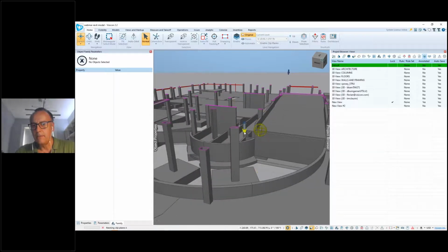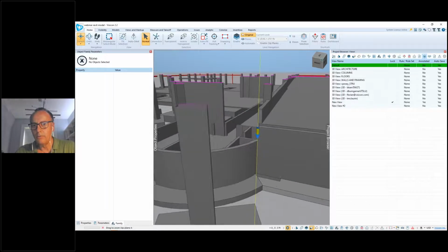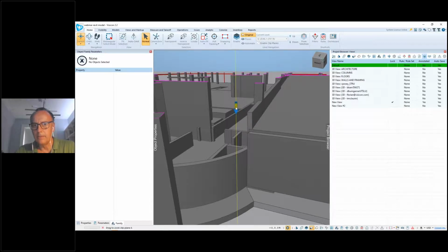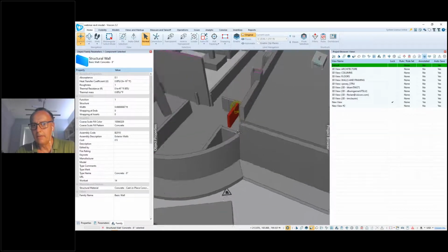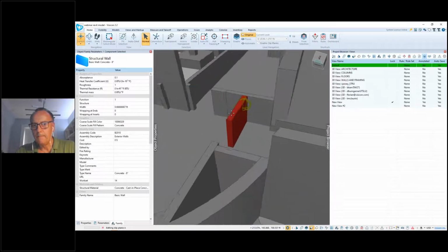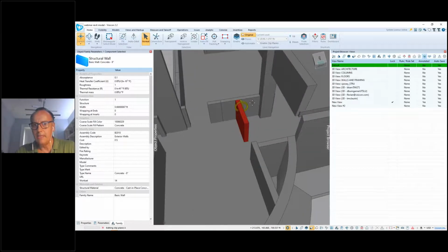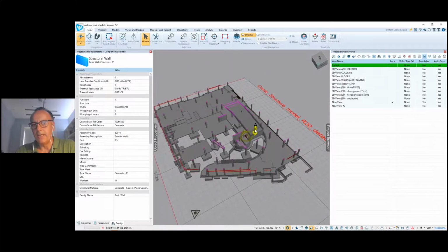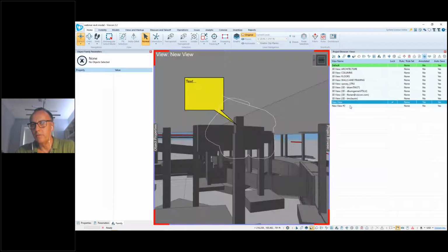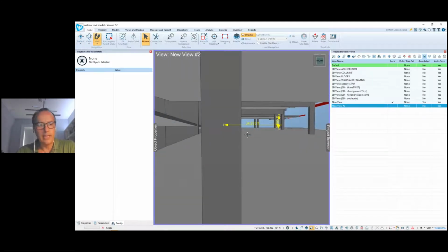I can grab this widget, move it to where I'm trying to understand exactly where. So here, I just need to bring this a little bit further down, right? I re-click to set that as my center of rotation, bring this over, and can come down and can see exactly what the size of these walls are. So for example, I can confirm that these are modeled as 8-inch walls, right? So zooming out, again, you have very easy ability to navigate and zoom, create and maintain multiple views of your project. So that's looking at the structural model.